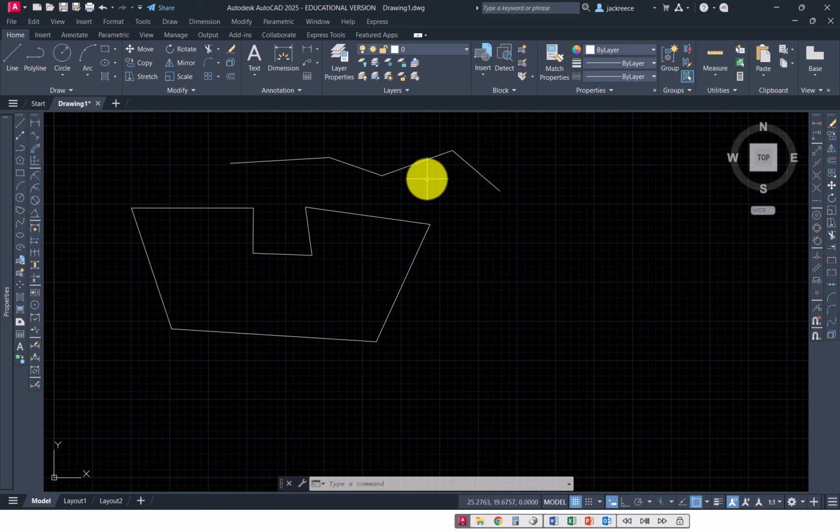And honestly, drawing architectural drawings, it's better to use the polyline command to draw the walls, because you can draw the exterior side of the exterior walls to the correct dimensions, and then use an offset command to copy that to the inside, the correct distance, and then you've got your wall thickness drawn.